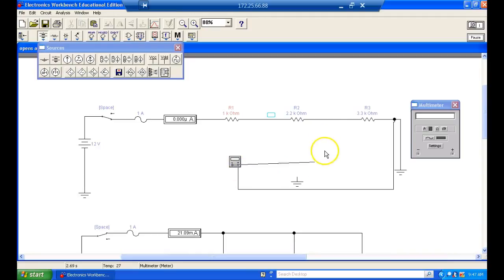A while ago, this resistor dropped 6 volts. What does it drop now? That's 0. It's just negative. So it's dropping 0. Why is it dropping 0 volts? There's no current. It still has resistance, but to get a voltage drop, V is equal to I times R. If I have no I, I don't care how big the resistor is. If I have no I, it's not going to drop the voltage. That makes sense, James?